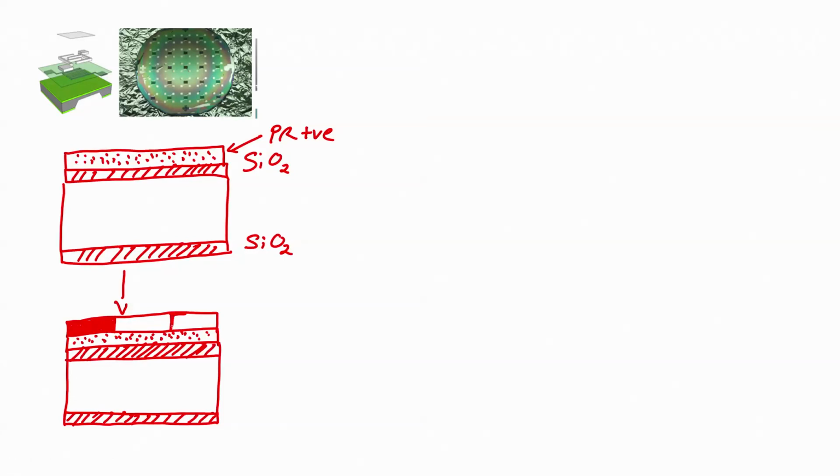That means we will create a window by etching silicon dioxide, because finally we want to create a diaphragm and then fabricate the remaining structure of the sensor, right. So, this is my mask.